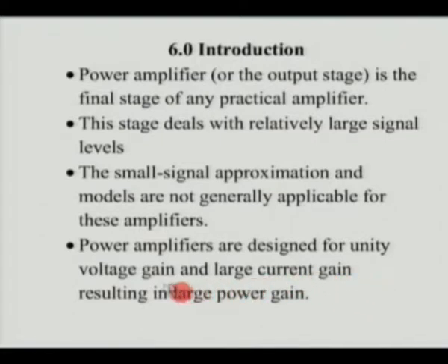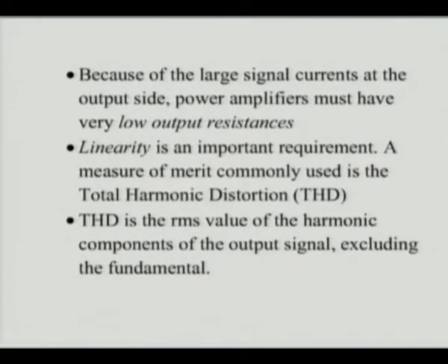So almost always power amplifiers are designed for unity voltage gain, and they have large current gain, therefore they have large power gain. So even though they have unity voltage gain, because of the large current gain they have large power gain, and we know that power gain is nothing but voltage gain times current gain.